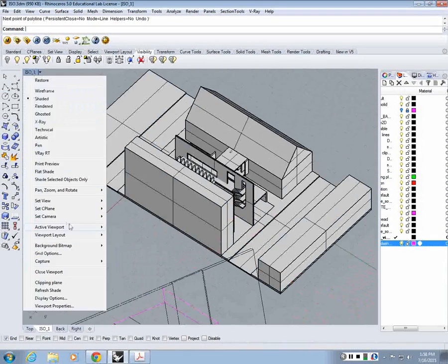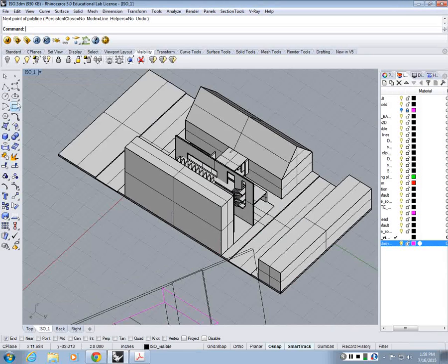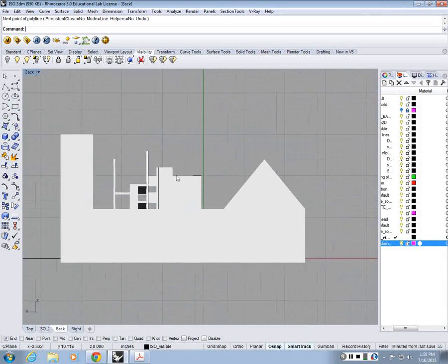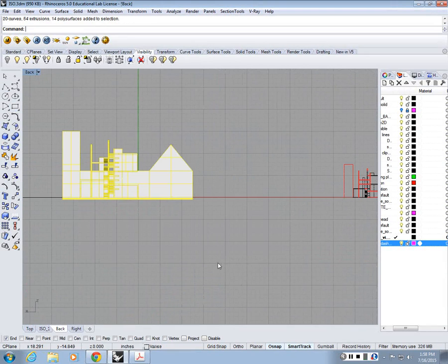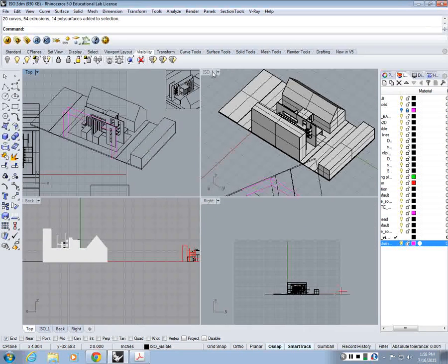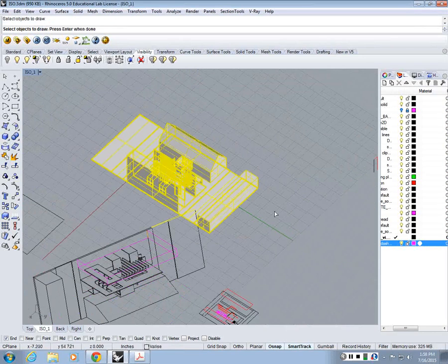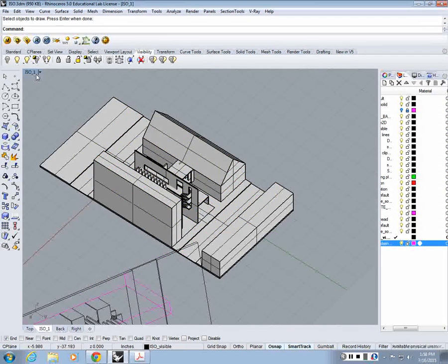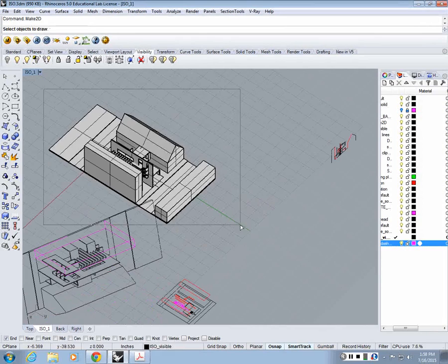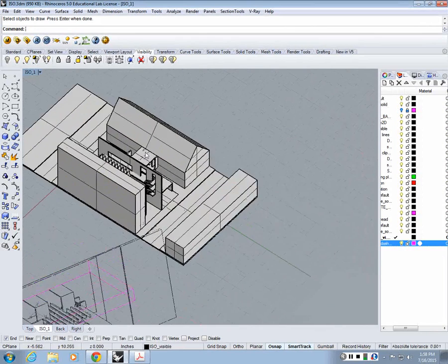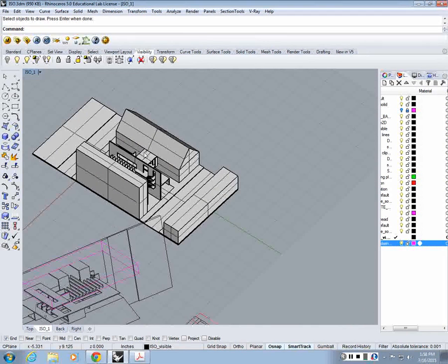Because it still uses a camera. I think that's the problem. It uses a camera with parallel projection. So when you go to an orthographic view, this is more accurate. So most of the stuff we did was from these views, so it's more accurate. But from this, I don't think it works the same way. But I see what you're saying. There's no other option, make 2D command either. So you basically set up like a distance to the model and just do make 2D. So you have to work with what you get basically as drafted lines. Okay?